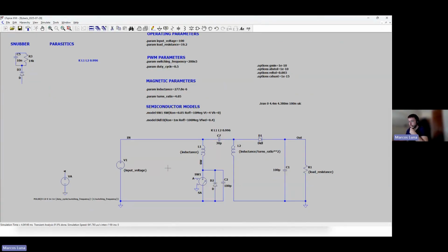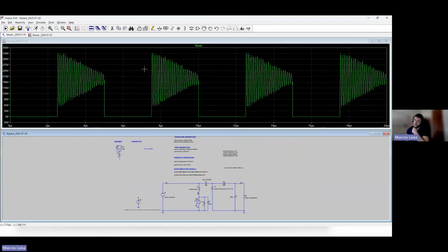And what we will see in the switching node is something more reasonable, okay? We have a huge ringing, but the voltage spikes are not like in the previous waveform. But here there is still a missing component that I talked about before, and we don't typically account for it in the circuit, which is the parallel resistor. This is a very difficult parameter to model in the system because it's difficult to measure. It depends on the BH loop of the material, and it can vary regarding the frequency and the temperature.